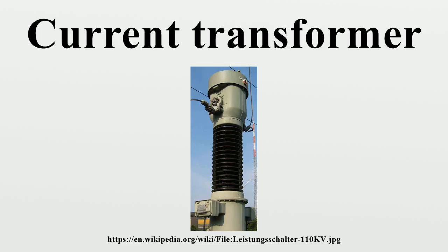Special types. Specially constructed wideband current transformers are also used to measure waveforms of high-frequency or pulsed currents within pulsed power systems. One type of specially constructed wideband transformer provides a voltage output that is proportional to the measured current. Another type requires an external integrator in order to provide a voltage output that is proportional to the measured current. Unlike CTs used for power circuitry, wideband CTs are rated in output volts per ampere of primary current.